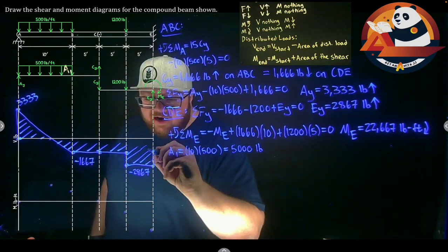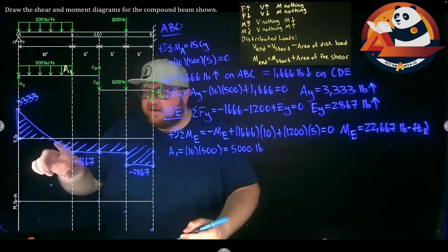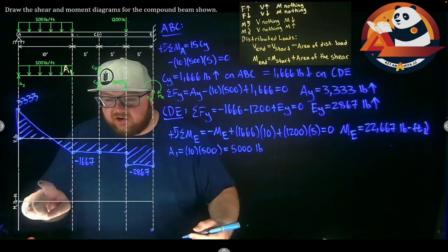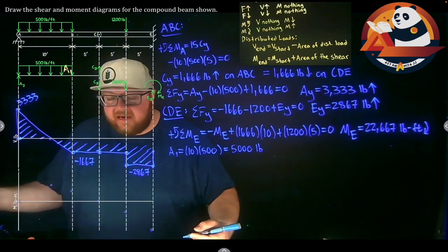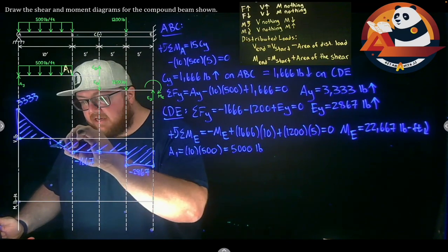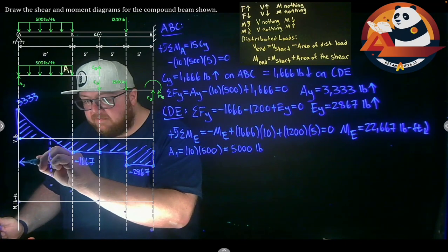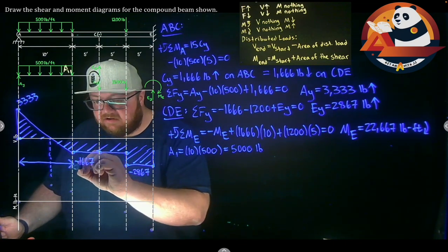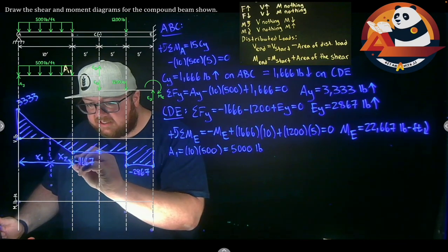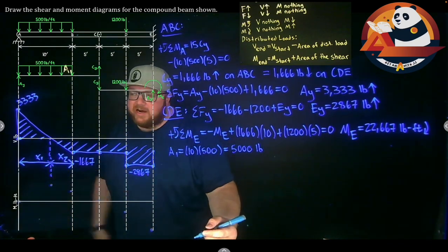From there, we can come on and say, well, let's figure out our shear moment or our moment half. To do that, I need to figure out where this is 0 at. That 0 shear should correlate to a max or a min moment point. So let's come in and dimension out some pieces here. We're coming down. We can go from the axis over two distances in here, x1 and x2. And I'll need those to get areas figured out. So let's do proportional triangles in here.